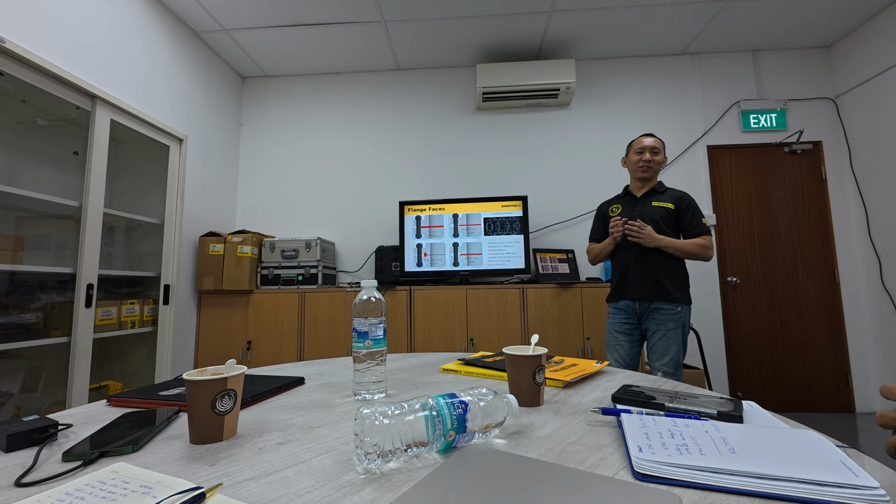It could be a custom design. Okay, you see, a fastener can be a custom design. So we also encountered some such designs as well, a custom one. Especially this usually happens when you come to equipment. Some equipment has custom fasteners, so it's a little bit more complicated because different sections you cannot do on the torquing. You might have to apply a different load calculation, a different load. Otherwise, it will neck the fastener if the torque is too high. Okay, so it really depends on the design.